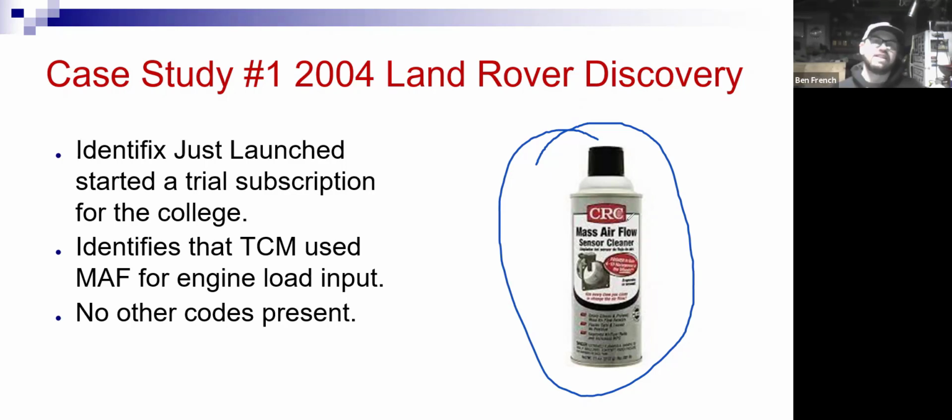And I've seen stuff like that happen over and over again. They'll put that transmission in the car, they'll clear the codes, they'll drive it around the block. Oh, it doesn't set the code anymore. They think they fixed it. They give it back to the customer, and it takes several days, even maybe sometimes a few weeks for that customer to meet the enable criteria. And then they come back with the same problem. So anyways, always verify your repairs, always use your service information.